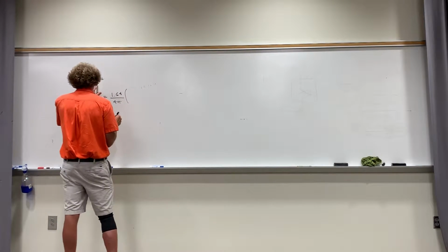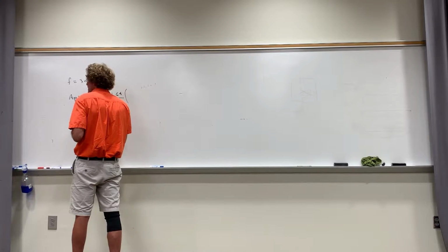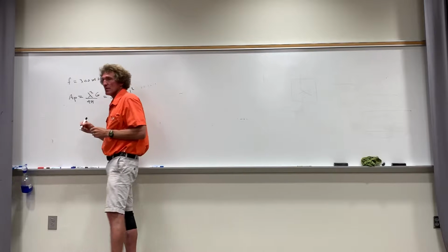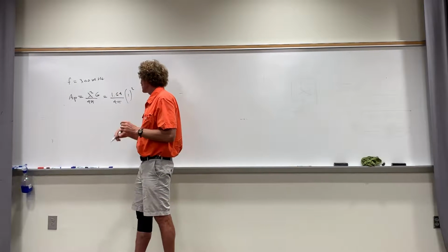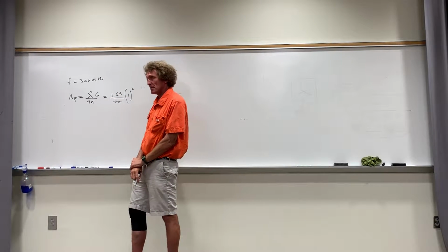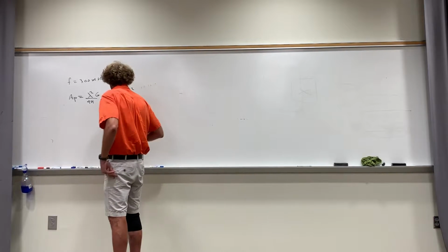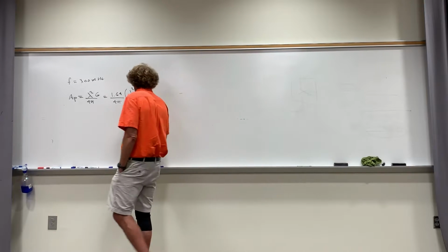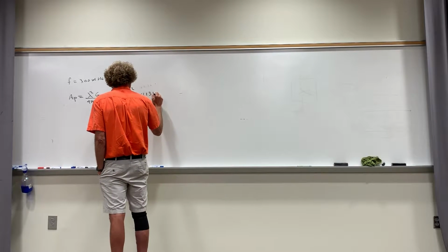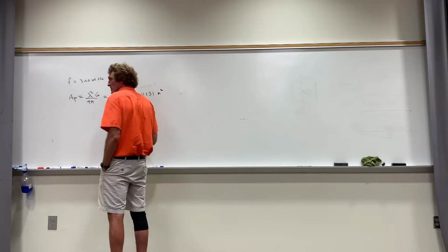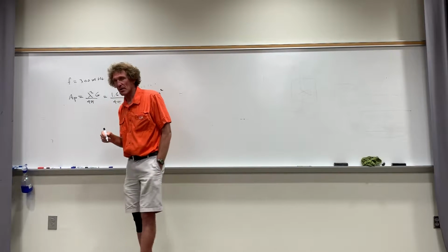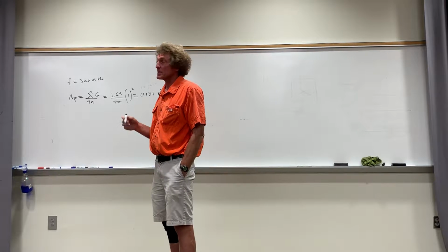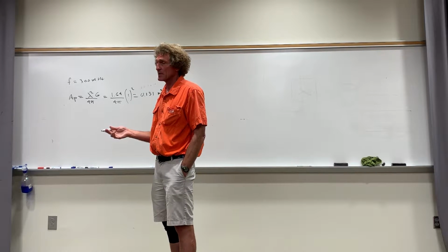At 300 megahertz, that's 3 times 10 to the 8 for c over f, which would be 1, correct, class? The wavelength would be 1 meter. That means 1.64 over 4 pi should be the maximum aperture. What do you get for that? Just to make sure his answer for this one is consistent. 0.131 meters squared. Is that what he had in the answer? Okay, check that box. We might as well do them, to make sure you know how to do them, because there are no solutions for these. These are just answers.